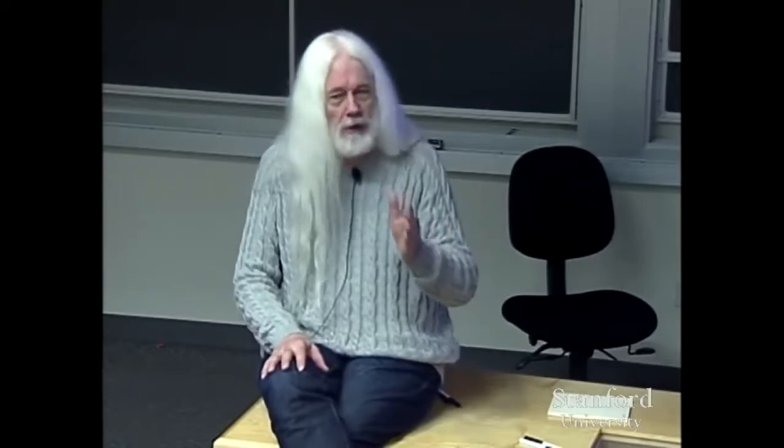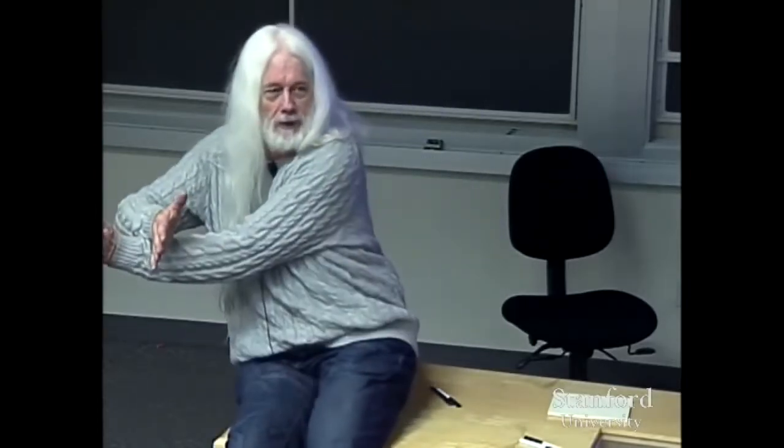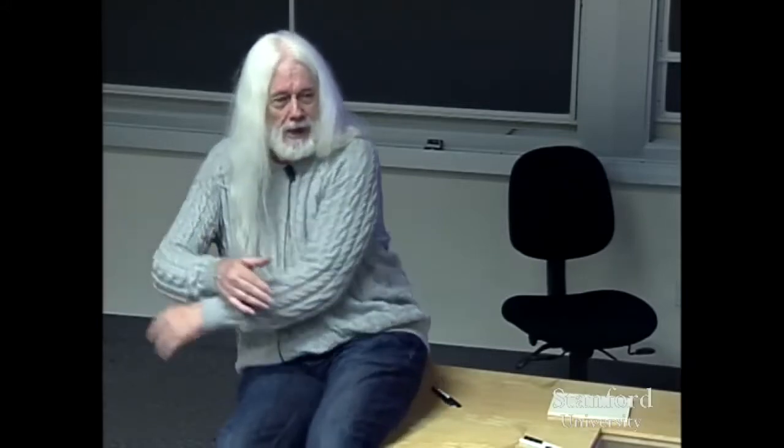In our situation, the programming model is a conveyor belt. All of the operations drop their results at the front of the belt and push everything else along. If you want to do an add, you can say, I want this value off the belt and that value off the belt. They'll be added together, the result will appear at the front of the belt, and everything gets shoved along again.